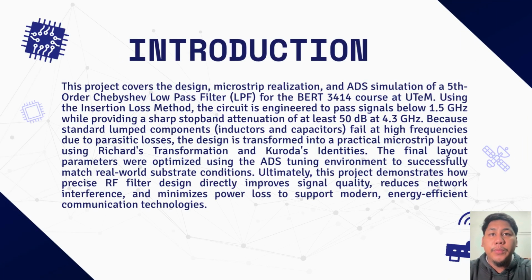Moving into the introduction, this project covers the complete design cycle of microwave filters, from theoretical calculation to practical microstrip realization and ADS simulation. We designed a fifth order Chebyshev low-pass filter using the insertion loss method. The filter is engineered to pass signals below 1.5 GHz while providing sharp stop band attenuation of at least 50 dB at 4.3 GHz. Now, why do we need distributed design?